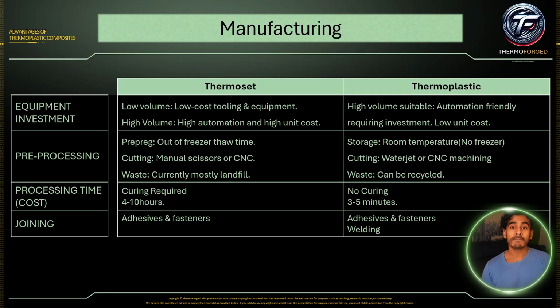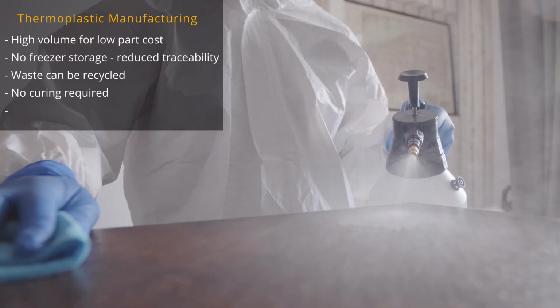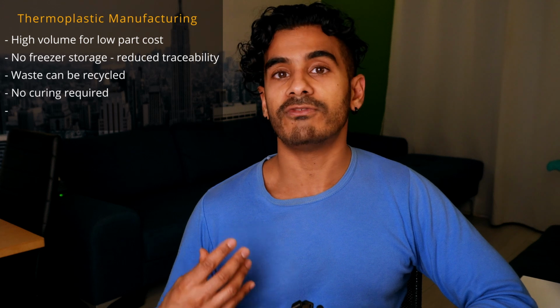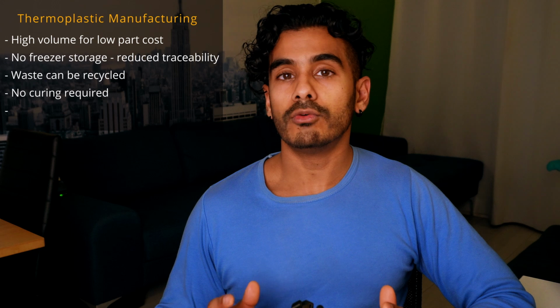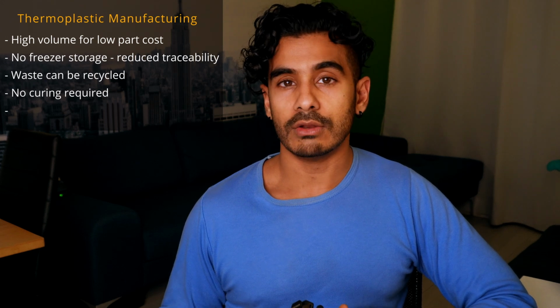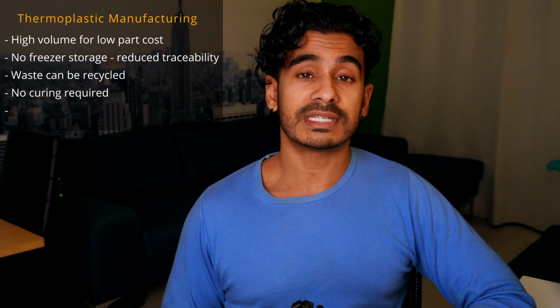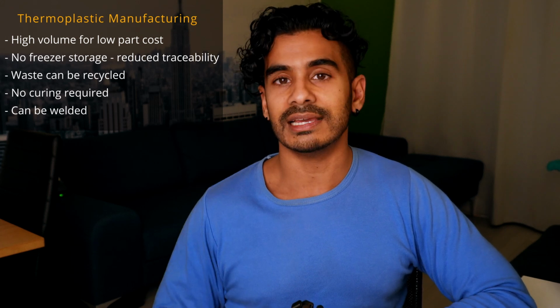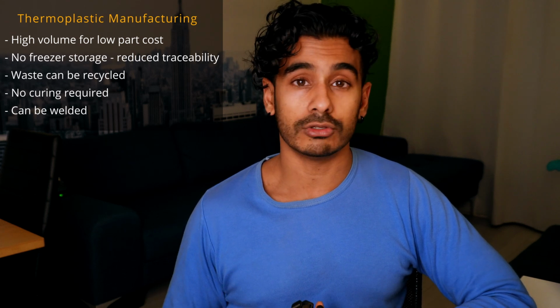And finally, the joining. When it comes to most composites, you can use adhesives and fasteners. Using adhesives on thermosets is a bit of a challenge because you have to do surface prep and use some fairly harsh adhesives. Whereas for thermoplastics, especially amorphous materials, it is a lot easier to get off-the-shelf adhesives, which are a lot cheaper. And the other opportunity is that because the material can be melted over and over again, you can actually weld thermoplastic composites. Say you're using ultrasonic welding, the process time is usually less than 1 second, so it's very fast. And if you're using, say, induction welding, again, these are extremely fast technologies. Your investment is in the equipment, but the cycle time in terms of welding is usually very, very fast, which is quite an opportunity, and we don't have any consumable cost.